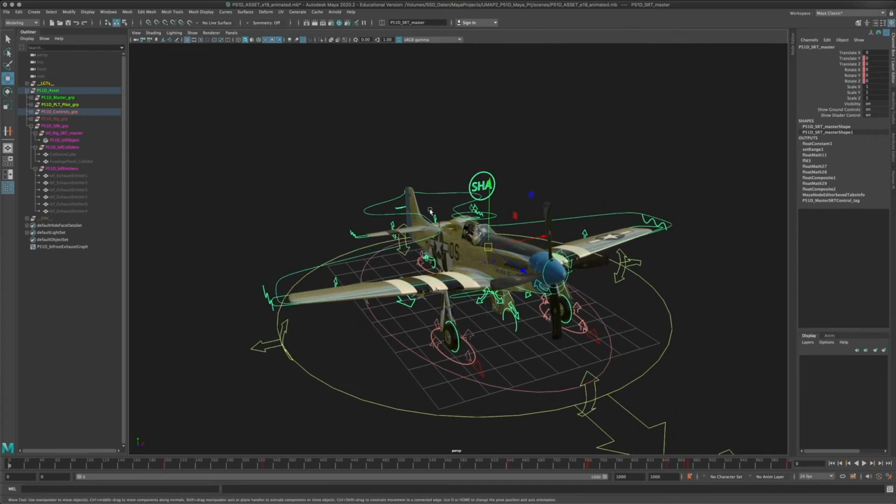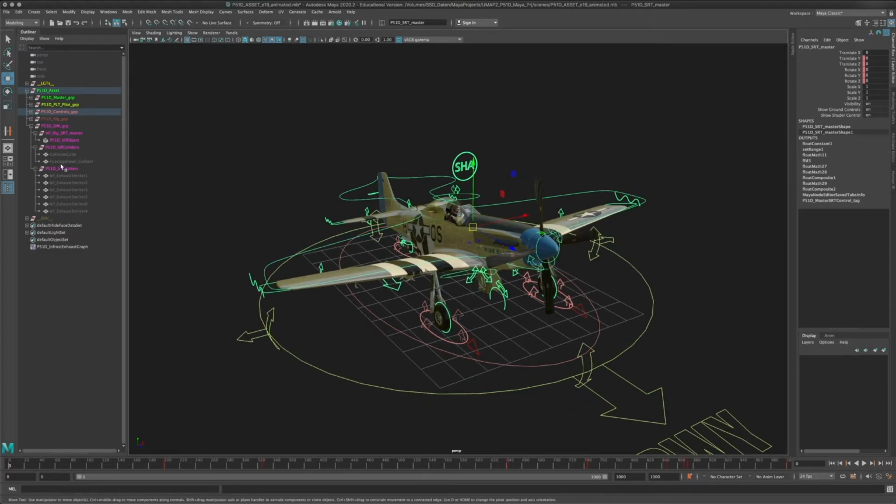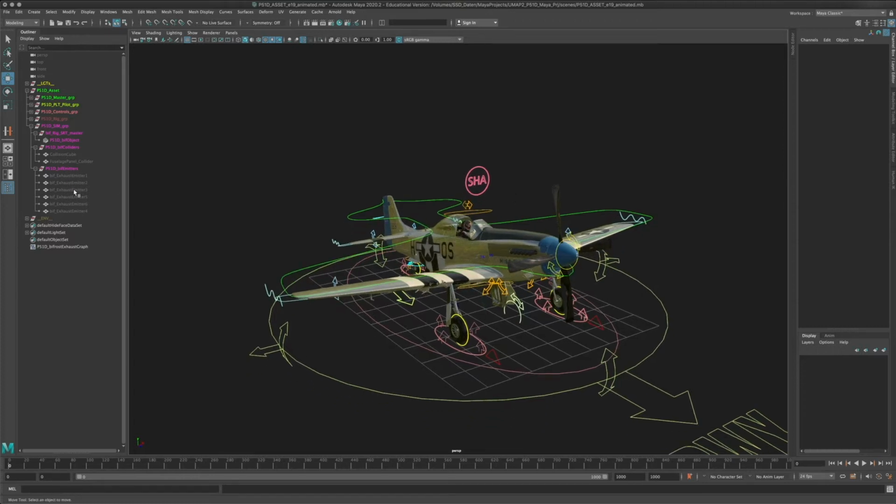You would do that differently in production, definitely, because you would simulate in place, since there might be a few planes starting their engine and the wind will be different wherever they are. It depends. Sometimes you only ever simulate one cache and you reuse that cache a lot of times and just give them the same cache. But I actually do it this way, and as I said, you can't retime or at least offset a BIF cache, at least not in any easy way, which I experienced on another project, which was quite frustrating.